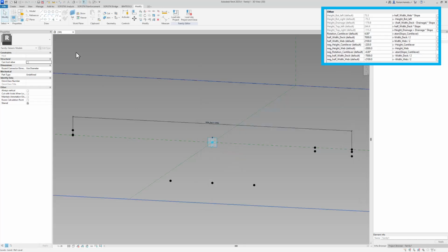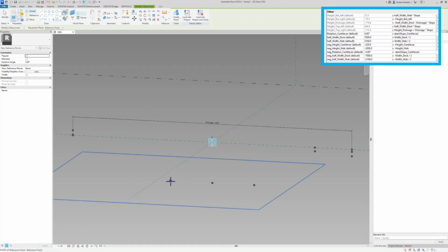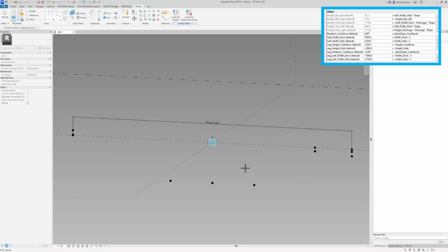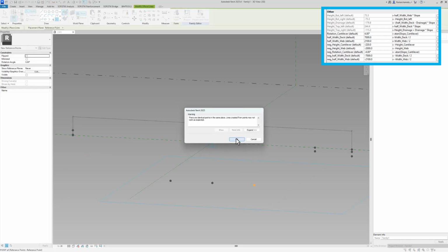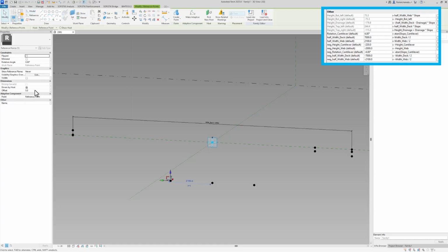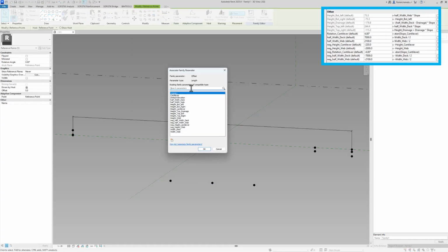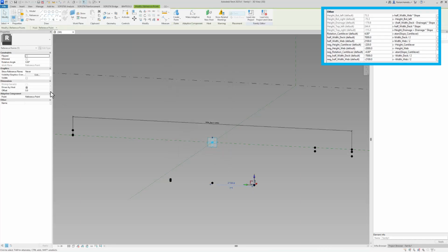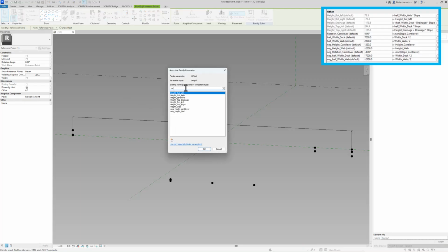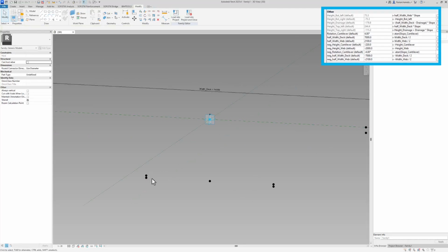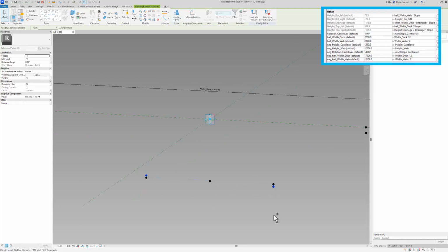Let's click on OK. And at this point, we are done with creating our horizontal and vertical reference points. And we will use the last part of the parameterization. Let's have our height bottom left, height bottom right. All right, so these 2 points will be my references for the geometry.